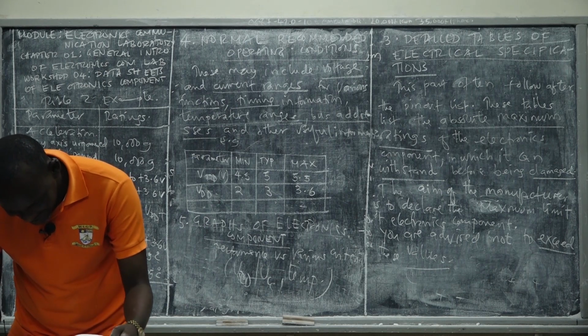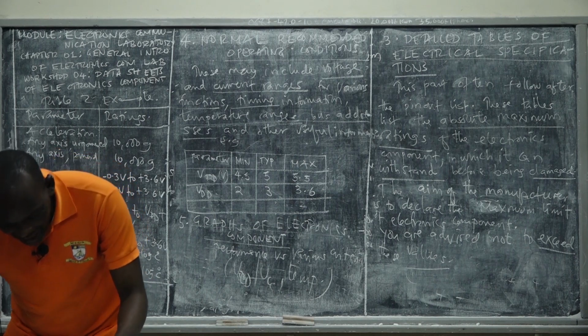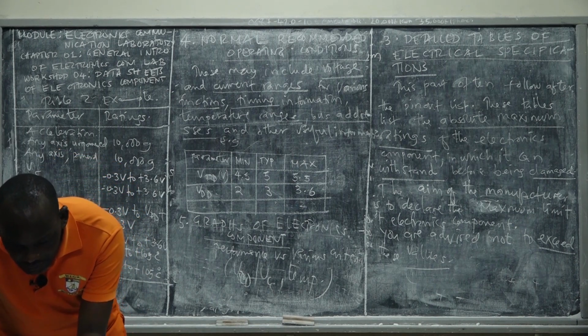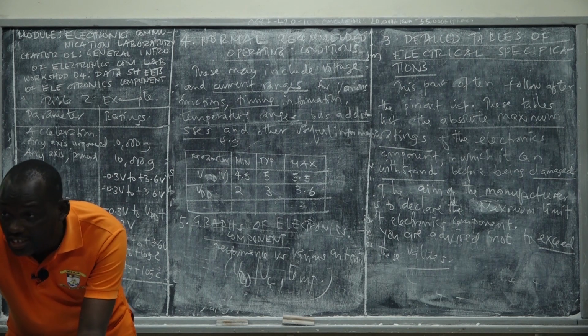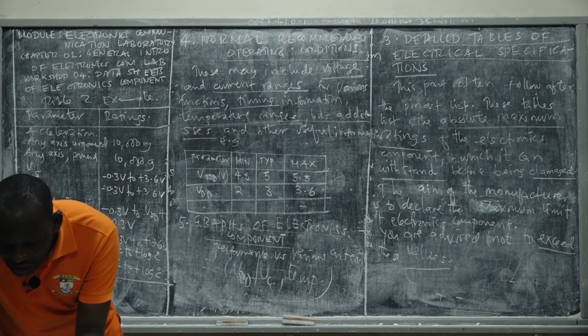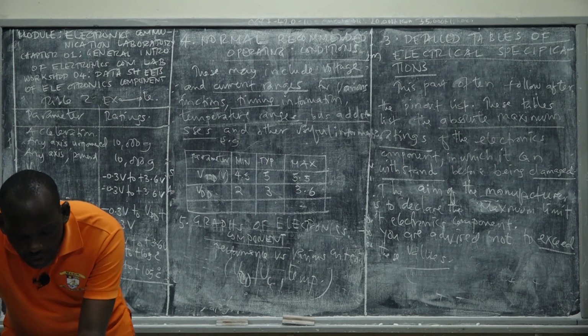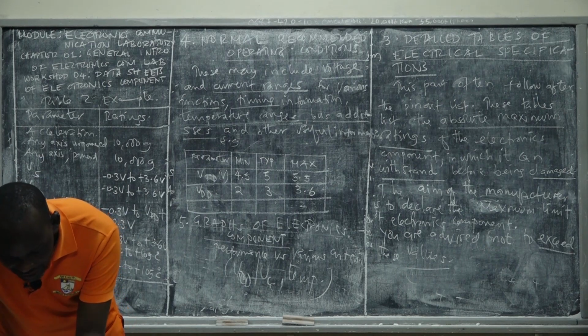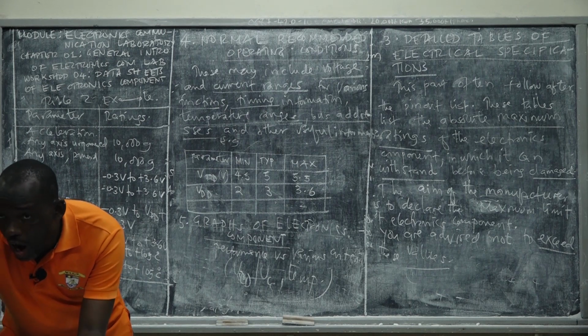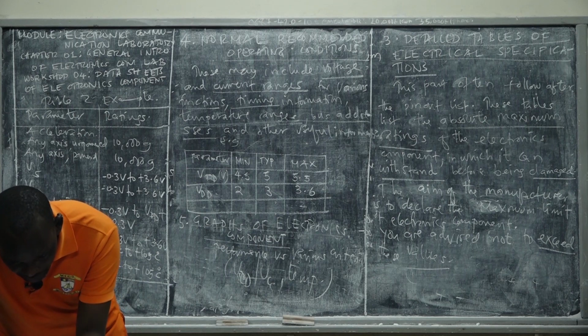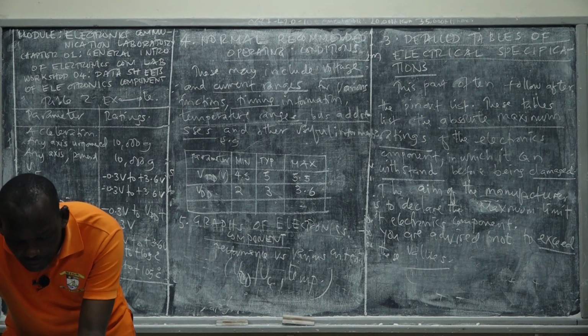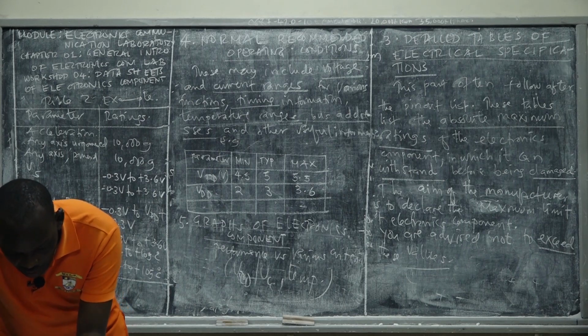You are confused there? Then for page number 6, we see pin configuration and function descriptions, because this digital accelerometer has an IC, called the ADXL345. Go to page number 6, and that IC has how many pins? 14 pins. What is the name of the first pin? VDD, right? What is the name of the last pin? Serial clock pin. Say serial clock pin. And then you have its descriptions.